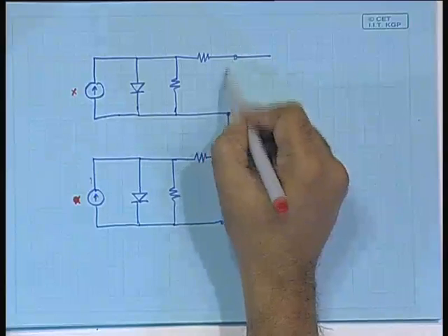If there is a cloudy sky, no problem, but then all has to be shaded similarly. If not, if some are active but the others are shaded, still the behavior will fall drastically. So, sometimes in some systems they add an additional diode across something like this, this is the terminal.